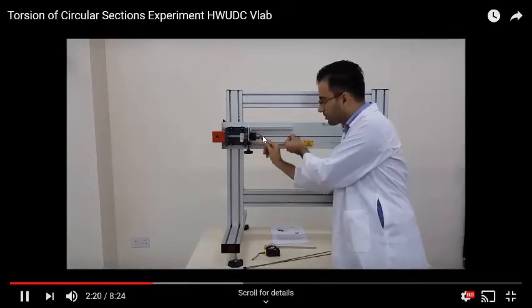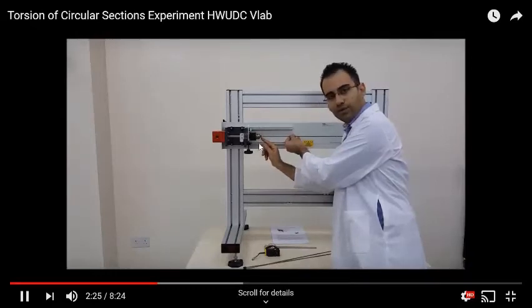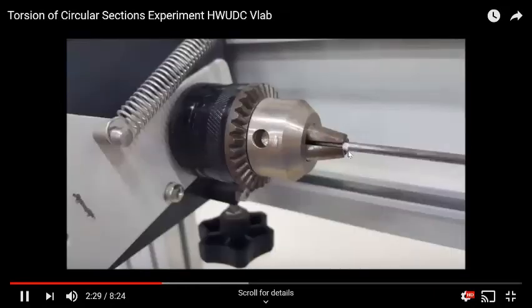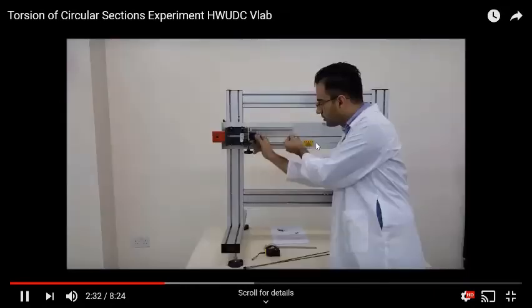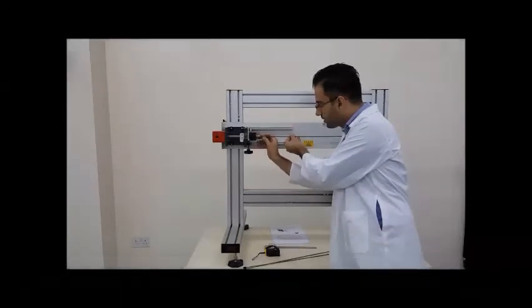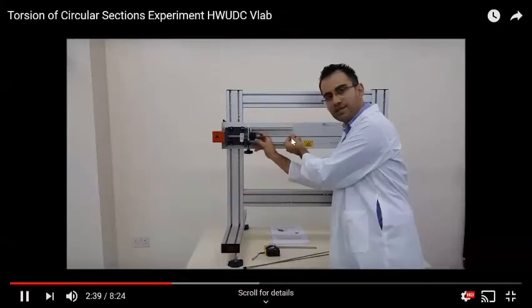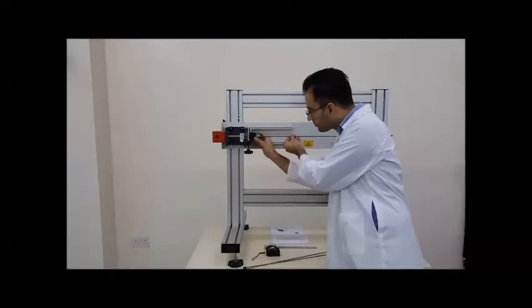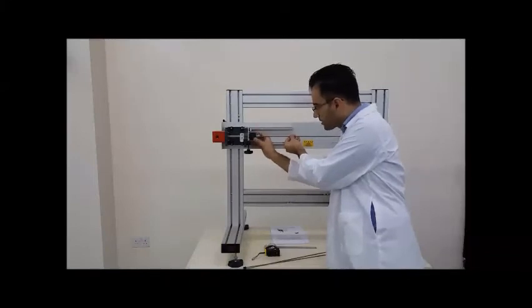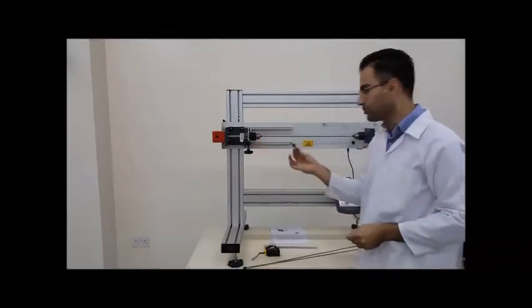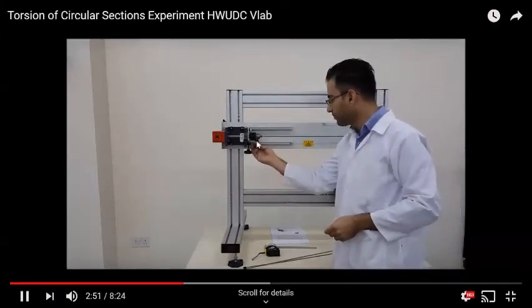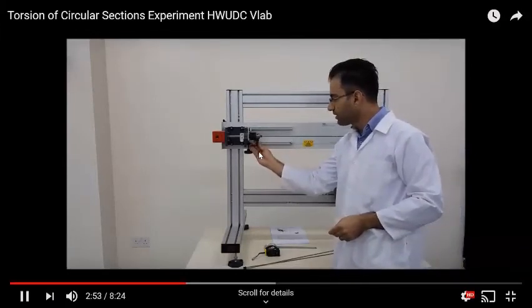So now you're going to input the rod into here, and then you're going to try to tighten the chuck down. But make sure you are at that mark that he marked right there. And what you've got to think about is as you tighten that chuck, that grip is going to go out. So you need to adjust your rod to make sure you still get the mark at the end after that grip comes onto the rod. And then after you do that, you take that key to tighten it down.